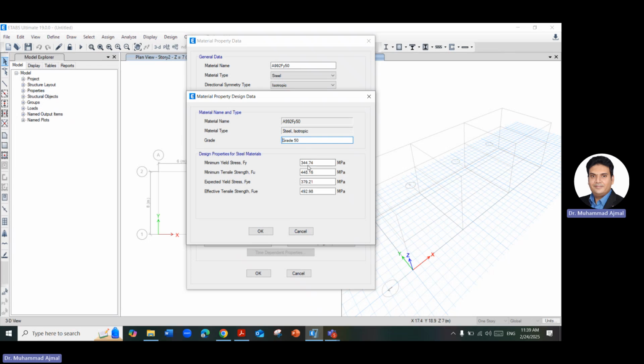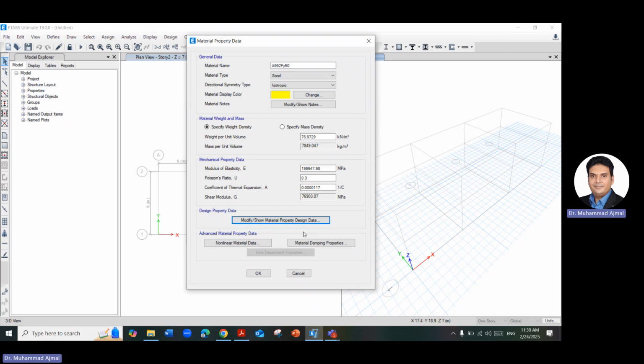If you are taking steel design with Dr. Abdul Hamid, what yield strength is he using? 300, 350, 275 megapascal. So if you look here, this is around 345 megapascal. So this is related to the structural steel, which is used for the steel design. Then you have the ultimate tensile strength. So these properties are already there. I just explored one for you.